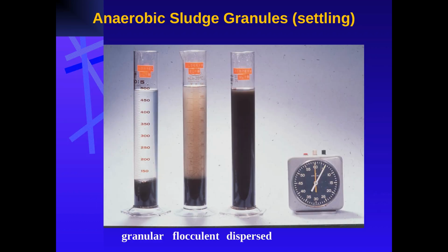This image shows an anaerobic lagoon used for treating wastewater from a food and beverage processing plant in Washington. Anaerobic lagoons are a simple and cost-effective form of anaerobic treatment, but they typically require a large land area and have lower treatment efficiencies compared to high-rate systems.